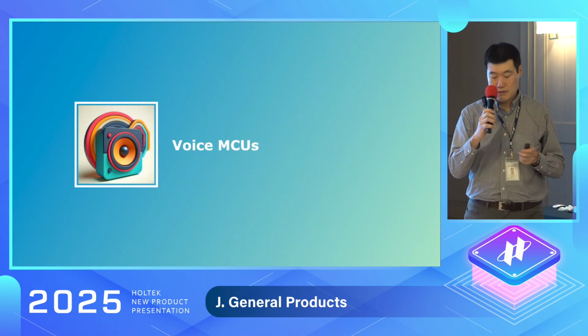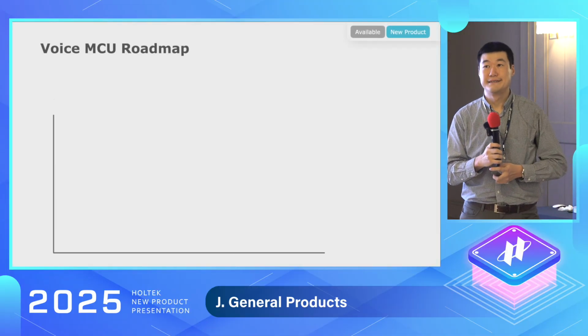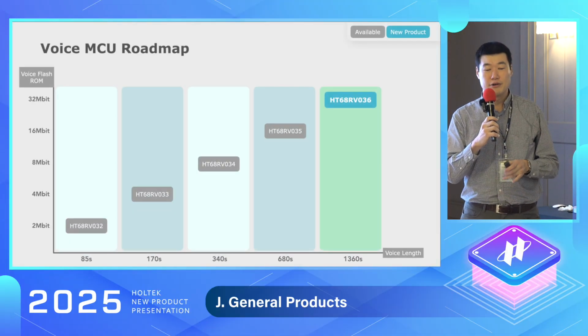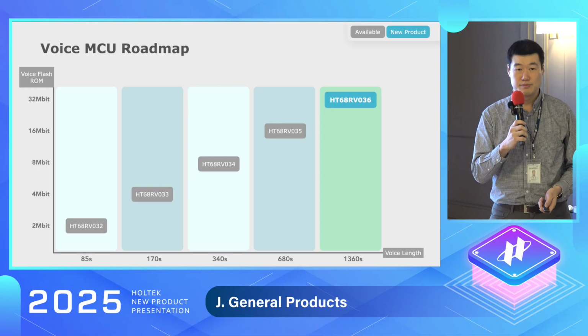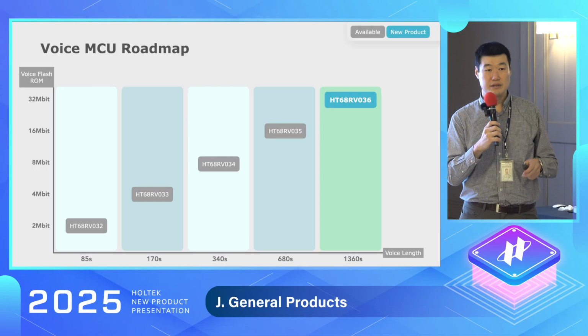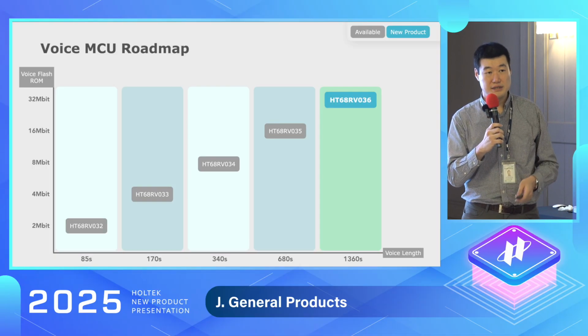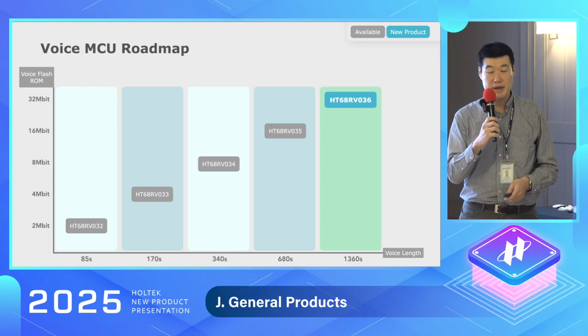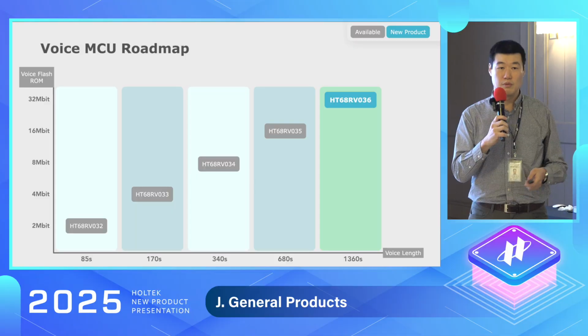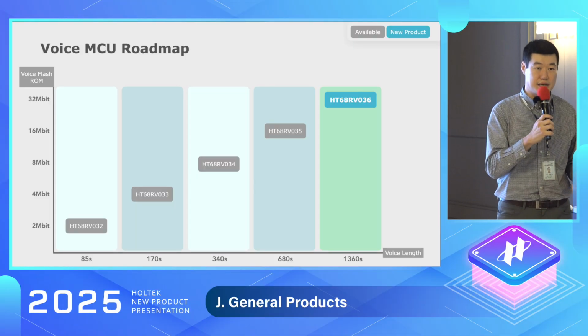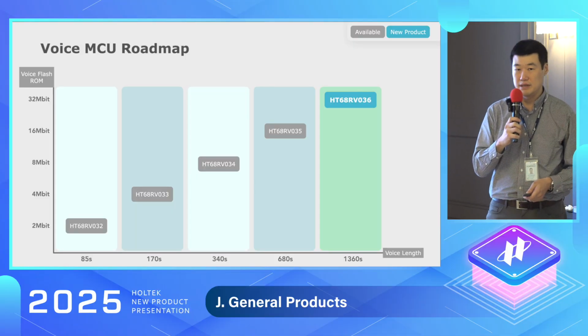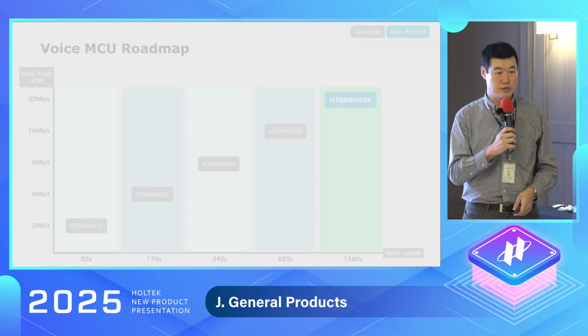Let's talk about our voice MCU. So Holtek already has many voice MCU products. This year, we enlarged the flash size to 32 megabit, and it can store up to 1,360 seconds. That's equal to 22 minutes. Let's take a close look.